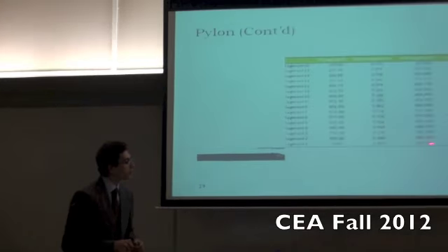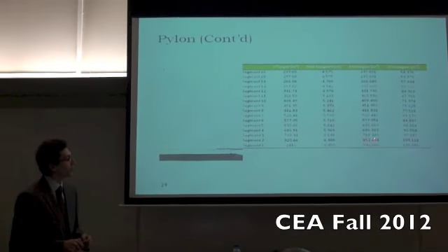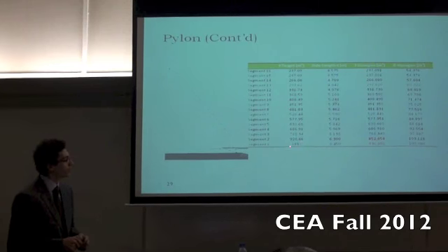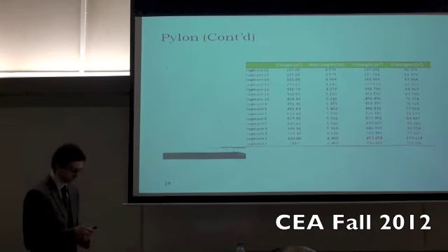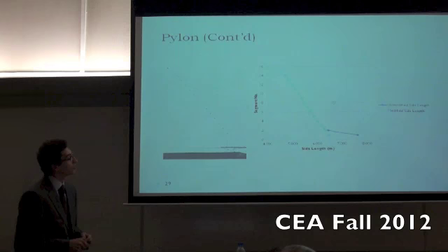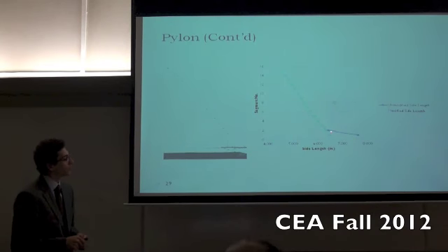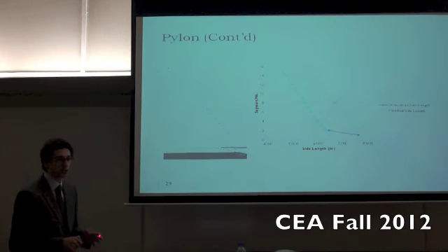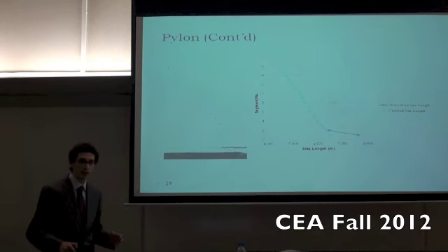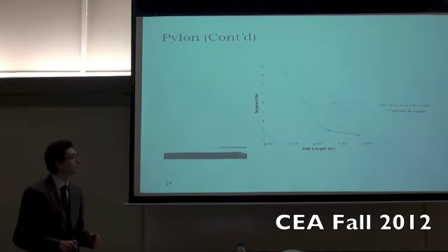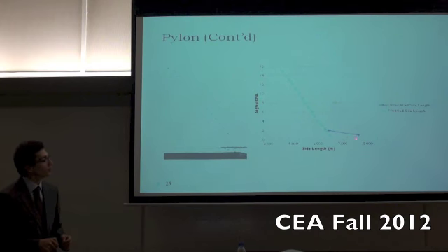You see here at the very bottom, the first two segments have lower values than the actual ones. This was due to the fact that if we needed to calculate the actual moment of inertia directly, we would have to get a hexagonal shape with a side length of 8 meters, which would contribute to a very large area, which was not permissible in our case. So we had to reduce the side length in order to make it vary smoothly all along the pylon with small modifications.